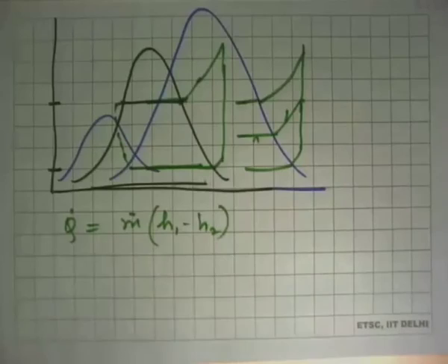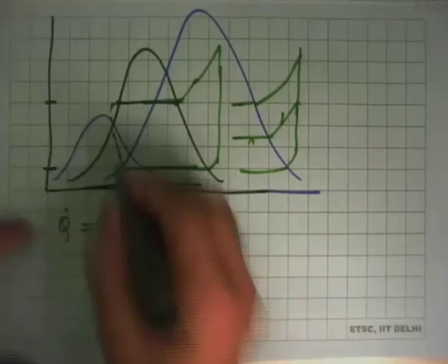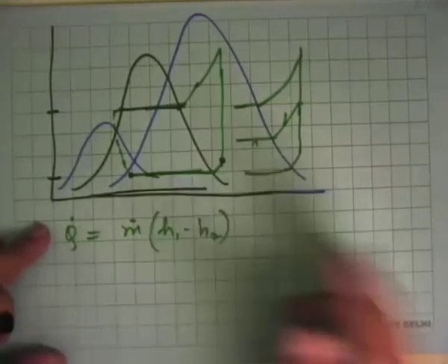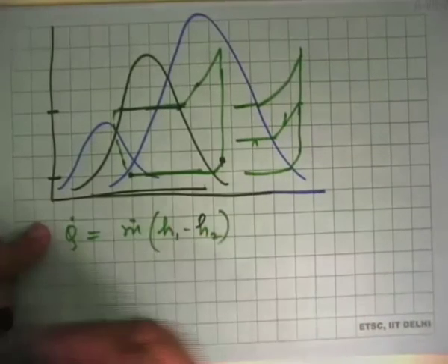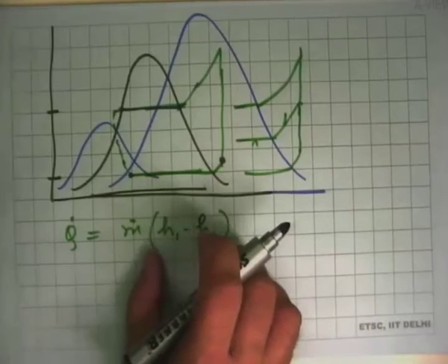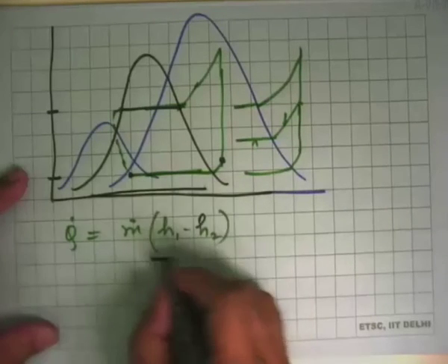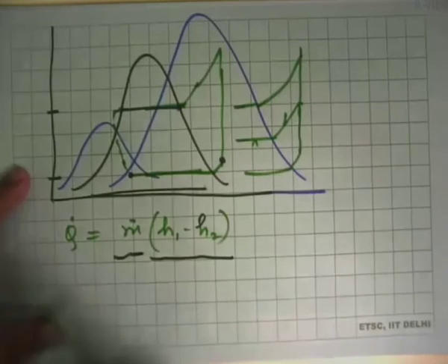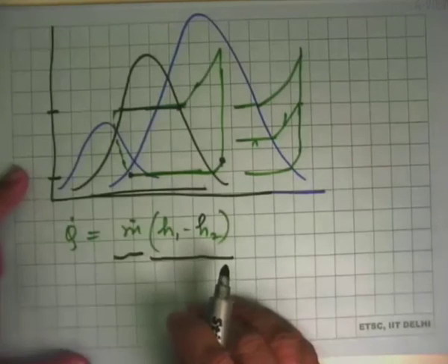Now, do I get a sufficiently large delta H from this state to this state? And if you see that problem in the assignment, you'll find that for some refrigerants this value is a few hundreds. For water, this value is a couple of thousand. So you'll say, good, great. For water, this is very big, so I need a very small flow rate. Water is a nice refrigerant.